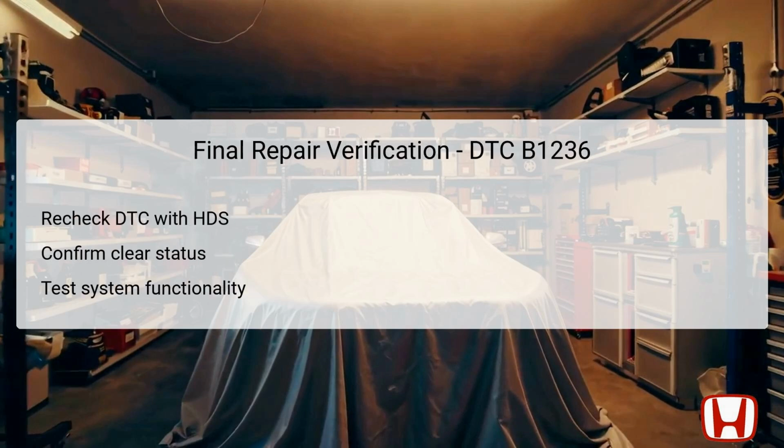The final repair verification step involves a thorough re-evaluation of the entire system using the Honda Diagnostics System, HDS. By checking for any remaining diagnostic trouble codes, DTCs, the technician can ascertain whether the repairs have been successful and that the system is functioning as expected. A confirmed clear status indicates that the DTC B1236 has been resolved and is no longer present.